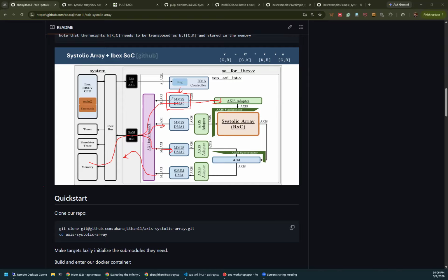And similarly, on the AXI master side, in the full AXI protocol, as I think I mentioned last week when I talked about AXI, you can issue requests. You keep issuing multiple requests, and you don't have to wait for the responses to come before you issue the next request. So you can have multiple outstanding transactions, right?